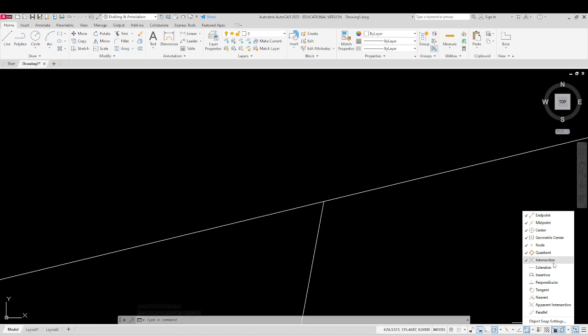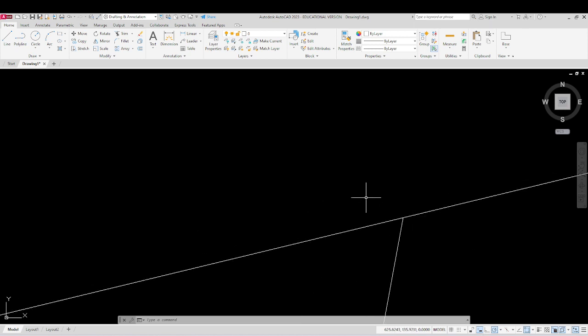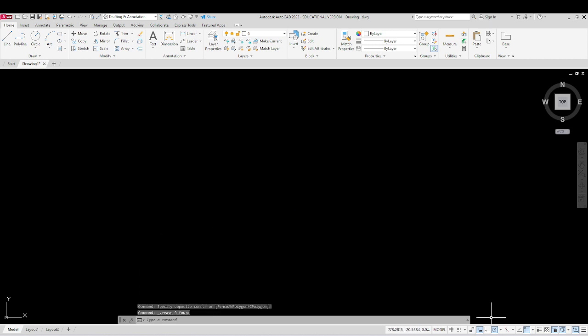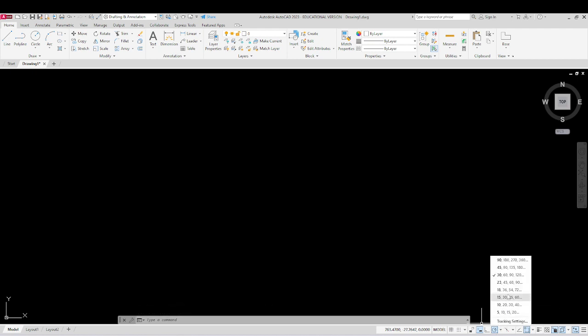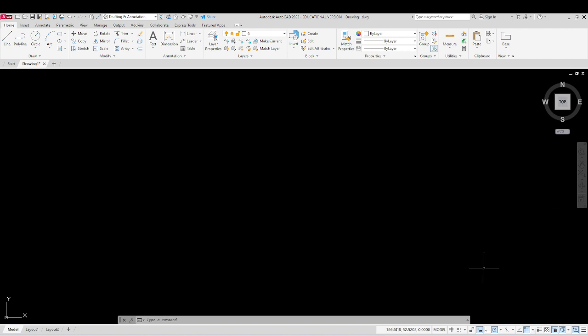Okay, but better we'll turn this off. Will not be requiring it. The mostly used ones are midpoint, end point, center. Will have the object snap turned on till intersection. Others should be turned off. This setting you should remember. Okay, so for orthographic drawing, orthographic projections, we should have these settings that I've told you: the dynamic mode, and then polar tracking with 30, 60, 90, and then object snap, and the settings in that you should have turned on. So this is what is object snap.